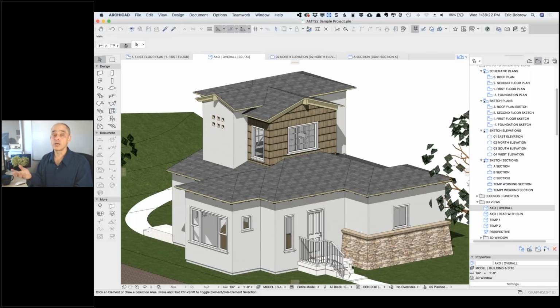And of course, ArchiCAD usually redraws pretty quickly. Now, if you're exporting to DWG or something like that, sometimes it's good to turn off fills or simplify them, because on the other end, they may get them as a whole bunch of little lines and say, God, it takes so long to clean up your drawings. So maybe send them something simpler.